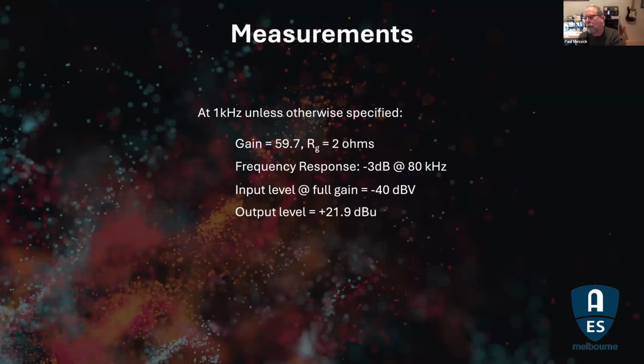And so you see that is a pretty typical number for things like feedback and load resistances. In the case of this design, I use 1K because in just the next slide, we're going to do the 0 dB gain version.